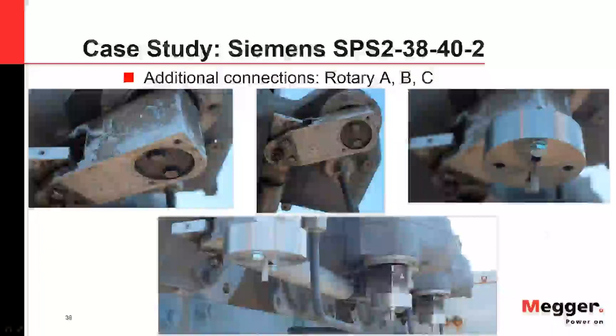And then additionally, even though the manufacturer recommends linear ones, we're going to hook up some rotary ones. You have one hooked up to A, B, and C phase. You'll see I took off the housing, and underneath there's the spline. As that linkage rod drives in and out, it rotates the spline, which takes us from linear movement to rotary movement, and then that rotary movement is converted back to linear movement inside the tank housing and drives the interrupter back and forth.